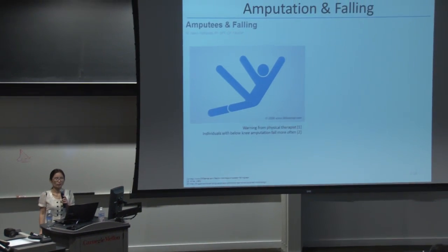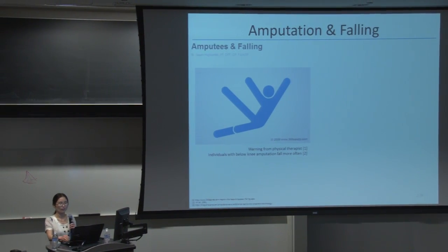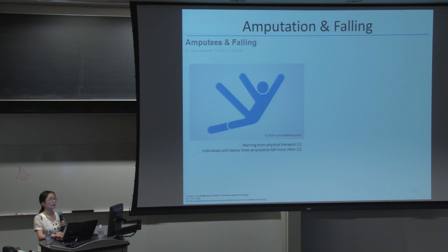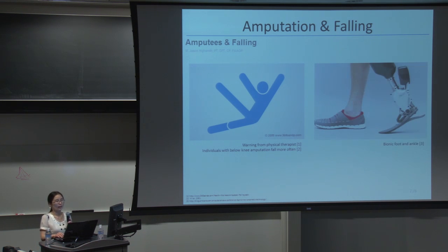Individuals with below-knee amputation experience higher risk of falling and fear of falling. This might be caused by reduced balance ability. To enhance stability, as you have heard in lots of talks, foot placement has got lots of attention. But for us, the ankle is the only accessible resource to help them. Hence, we got a question: can we help them using a robotic ankle to improve stability? And actually, can ankle actuation, especially push-off work control, improve disturbance rejection ability or not?